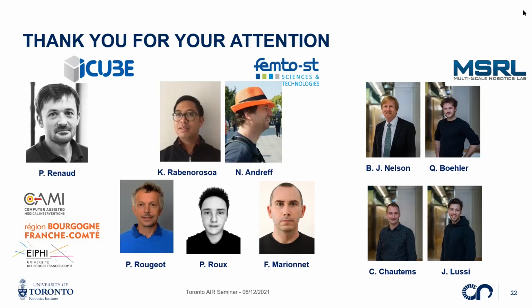So instead of using metal to build the rigid links that we see in industrial robots, trying to use biosourced materials, wood, or biosourced gels that come from algae. If we can make a robot entirely composed of these materials, without standard joints, with flexible continuum structures made of wood or biosourced material, we could obtain a robot which is biodegradable and cheaper to fabricate.